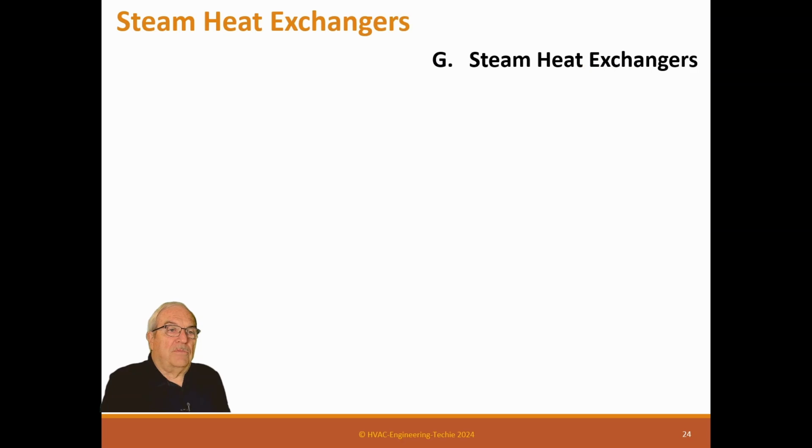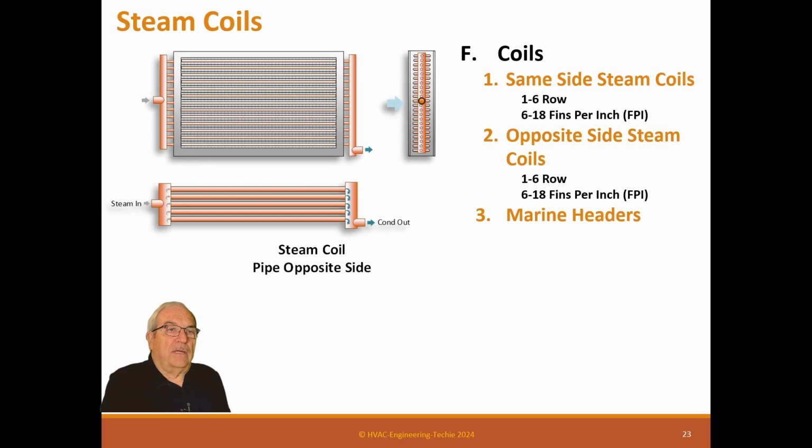Marine headers. The marine header basically is a cleanable header. So instead of a pipe here, it's a chamber where you can remove the cover and clean these. In marine applications, when you've got seawater, you get a lot of things coming in with seawater. So they basically are cleanable.